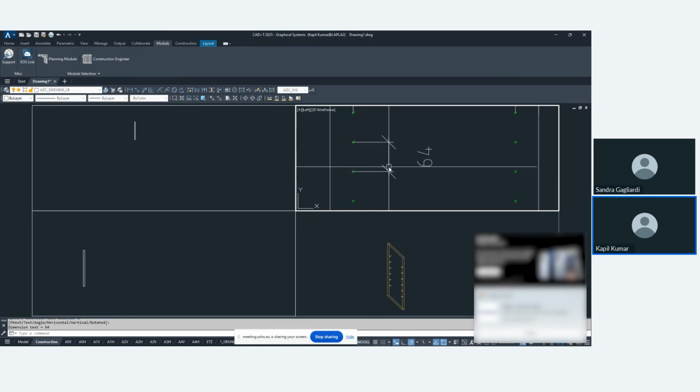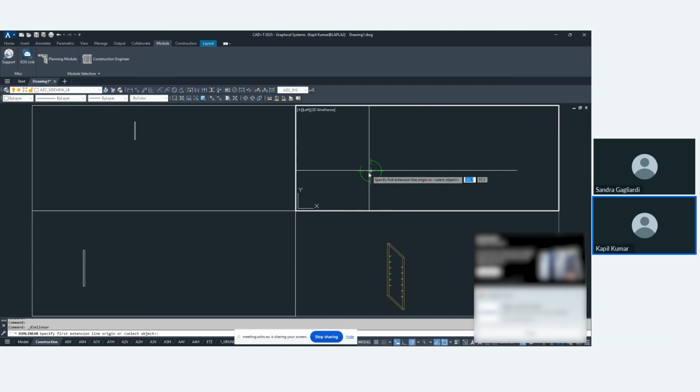But I kept here 100 mm and here 100 mm, but the system will follow as per the panel length, because the system will follow this grid pattern. So it will give us the nearest to 100, whatever we get nearby 100. So the system will give that dimension in that case.